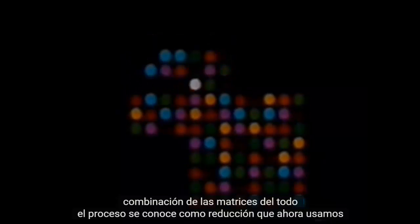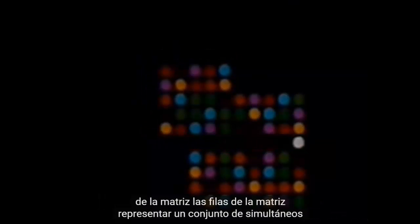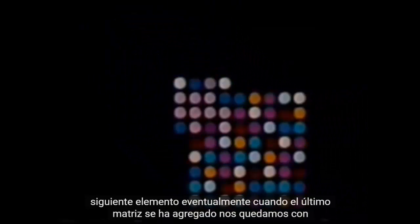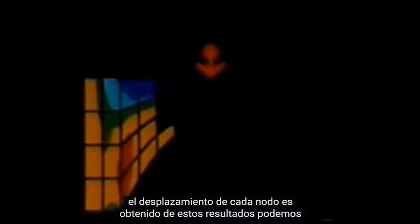We now use a standard procedure to eliminate part of the matrix. The rows of the matrix represent a set of simultaneous equations. We solve the first equation and substitute the solution in the remaining ones, repeating until finally we're ready to add on the matrix for the next element. Eventually, when the last matrix has been added, we're left with the solution for a single node. We can now use this result rather like a key, working backwards through all the equations of the system until at last the displacement of every node is obtained. From these results, we can quickly calculate the corresponding stresses.